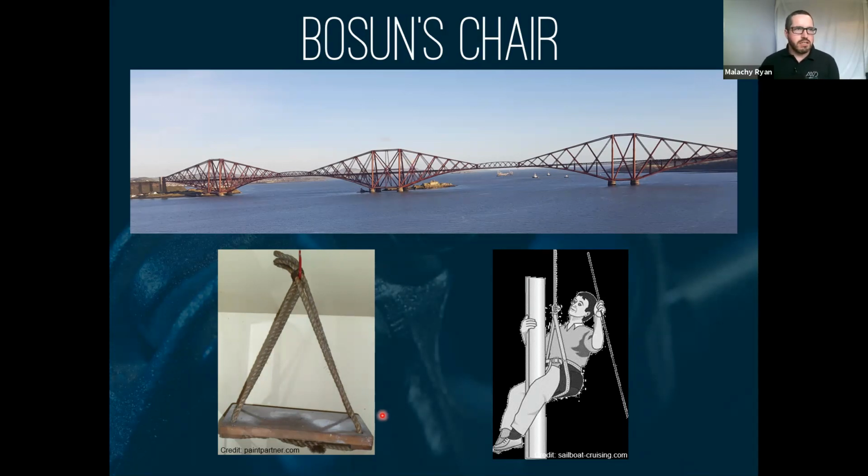While it's something that was used extensively in the past and there were lots of accidents on it, it still is something that's used in rope access nowadays, but it's not the primary form of support. It's actually just a rest device nowadays. I've used these in the past myself as well. When you're in a harness for a prolonged period of time, you do get quite sore around the thigh region and the chest. So you have the BOSUN'S chair, which you can have with you when you're working, and you can slide it under your backside basically, and it pulls you up slightly and takes the pressure off the harness, and it just gives you a bit of relief when you're working in that position for extended times.